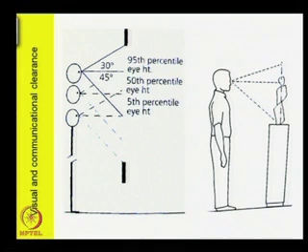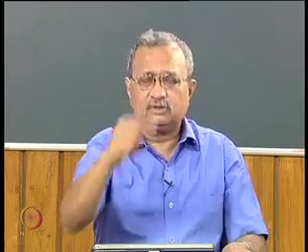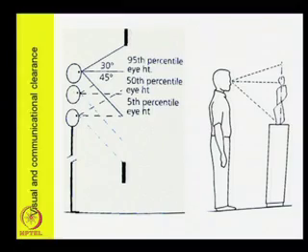At the counter, it is not only the physical reach of the arm, but also the visual clearance that is necessary, like visual and communication clearance. Here one thing we have to consider is people's height. When we talk to each other, the counter person's eye and the customer's eye have to be at the same level, or at a comfortable communication level. If a short, medium or tall person is there, then accordingly that has to be considered.